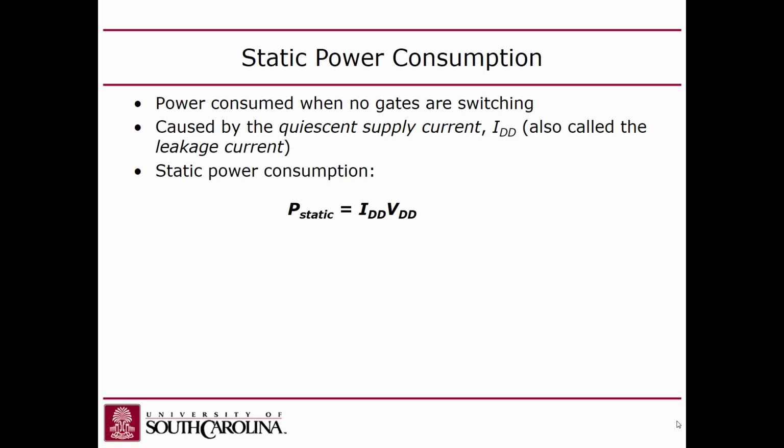No, there's still some leakage that comes from VDD down through these transistors, and then of course they go through these transistors because they're turned on, right? So the leakage goes down through the pull-up network. In this case, if I'm pulling down, we get leakage through the pull-up network, and then once it gets here, it's going to of course leak down into ground, right? And that's what this leakage current is, IDD. You guys with me? And this is power that's just constant. It has nothing to do with clock gating, doesn't affect it.